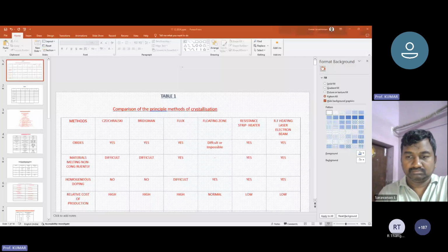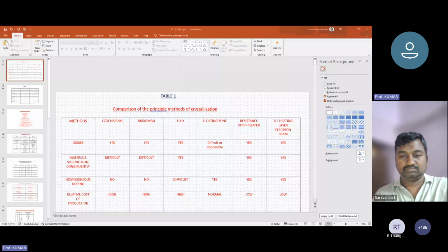Photoluminescence is an optical characterization tool, which is also very, very important in terms of understanding quantum structures. And FTIR is another technique which is used to measure very low trace quantities of impurities inside these kinds of semiconductors, only if they are optically active. X-ray diffraction is the basic fundamental tool, as you all know, to understand whether the material is crystalline or not.